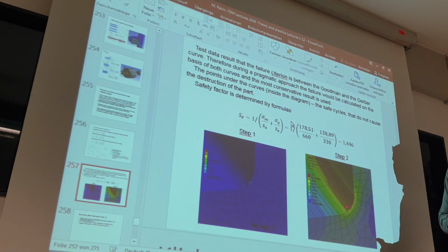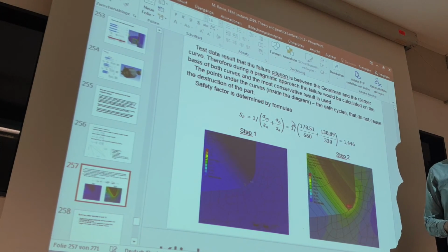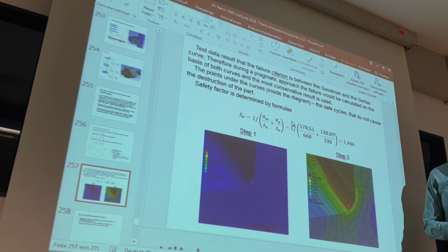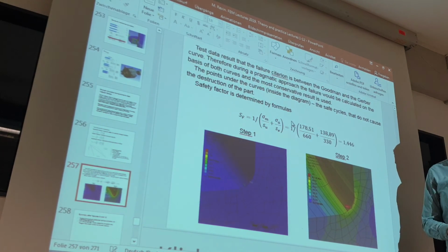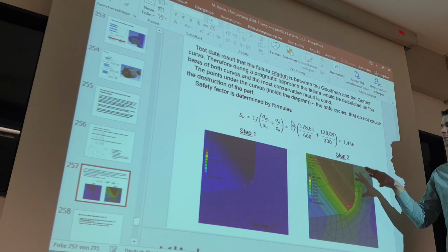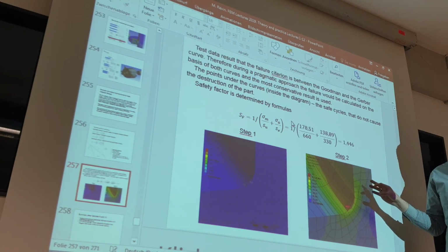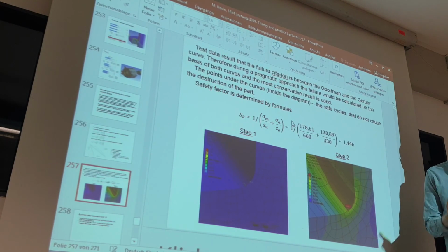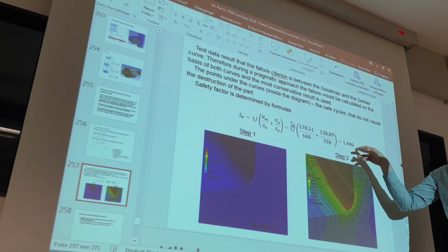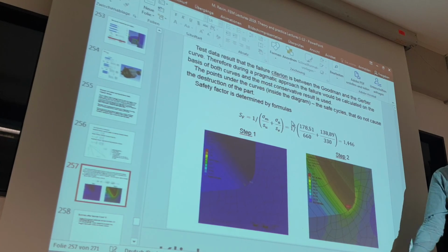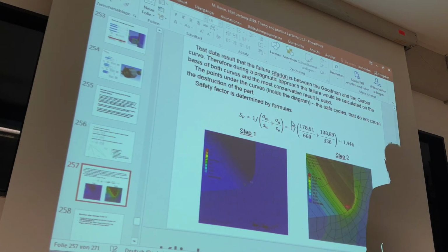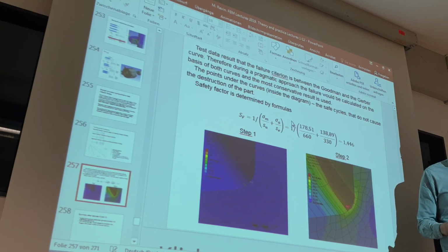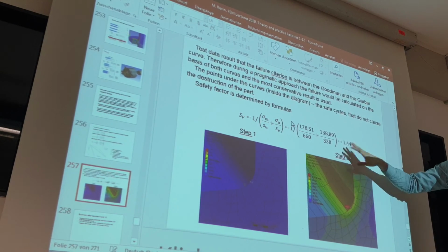For example, our part broke in reality after 500,000 loads and the target was 600,000 loads, and the simulation told us 1.2. If we do some optimization and see 1.3, it means I'm better, and now it has to work. But a target of 1.5 is normally safe.